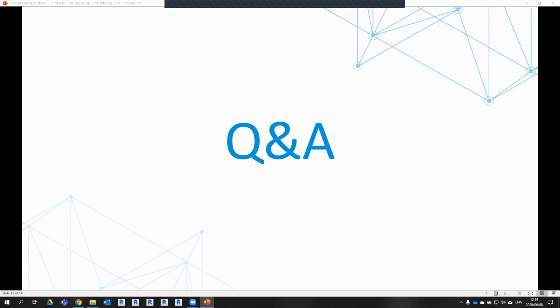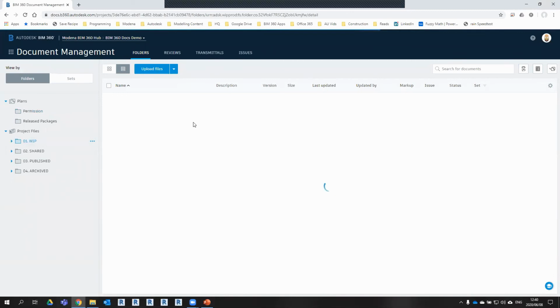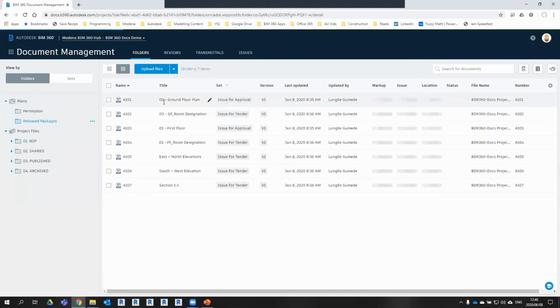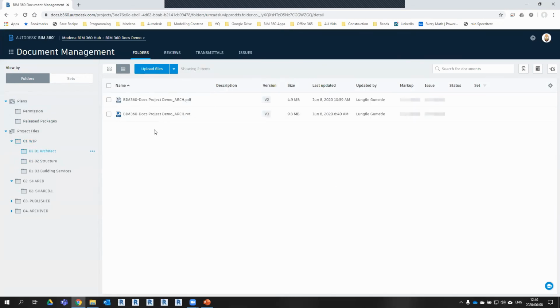Thank you. How can users keep record of what has changed during project uploads? So what I can show you now, unfortunately, this only works when you've got different files uploaded. Versions. I just want to get to those Revit folders again. Okay, so yeah, we have it. Okay, this will actually work. So here we can see the version control. So currently I've got three versions on this project.